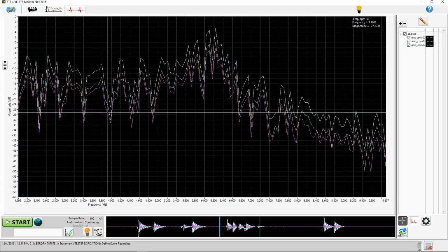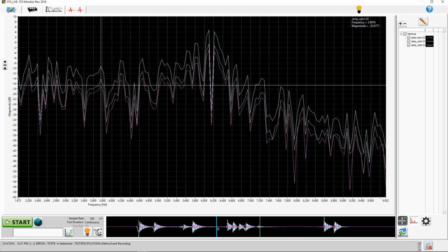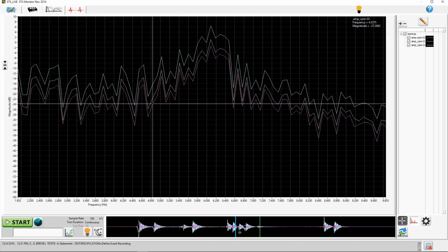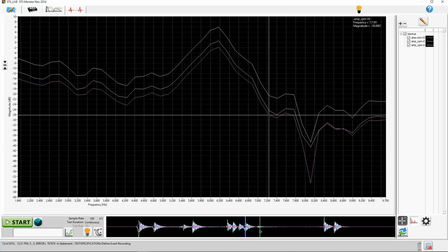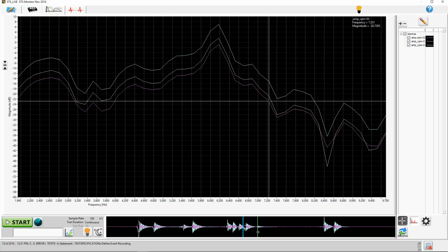In worst case situations, a resonance frequency starts, and then the next time we get a resonance, it is exactly in counter phase. You run an FFT over this area, and the first resonance is cancelled by the second resonance. You have to keep these things in mind when we start setting up FFTs and sliding FFTs.